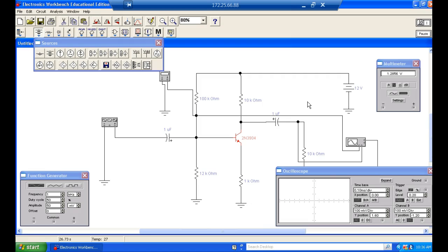If the bias is right, and we're not getting anything through the amplifier, then either the amplifier is not getting an input or something's going on with the output, right? You understand? If the bias is wrong, then something might be going wrong with the bias circuit.